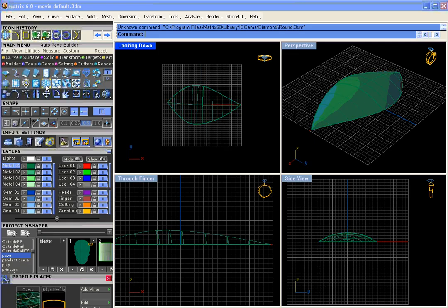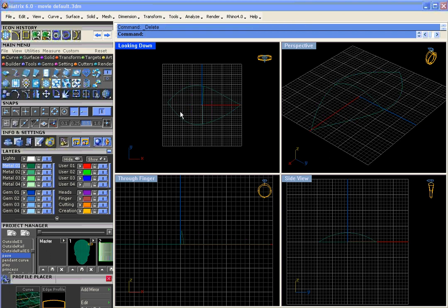It kind of starts to get confused. So you can't do the Pave Builder with a polysurface. It has to be a single surface. So using the point command or simply placing points in the corner and using those to sweep to allows you the flexibility of creating one single surface, which the Pave Builder will be happy with.